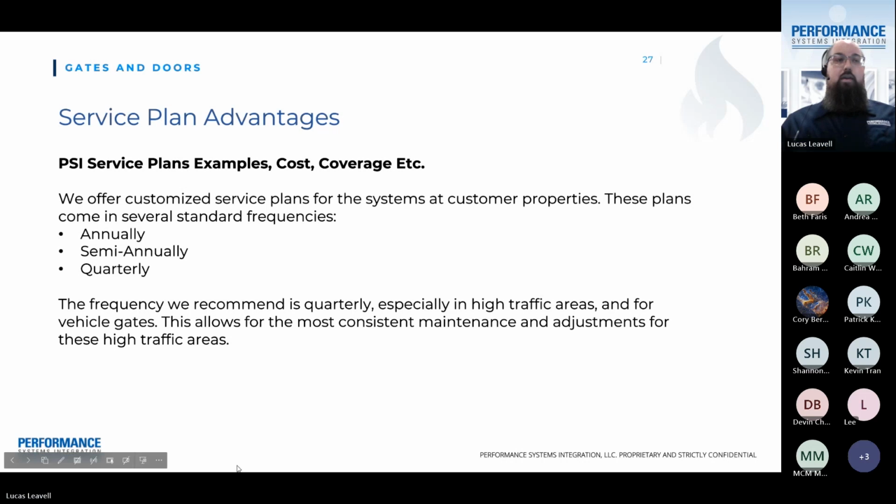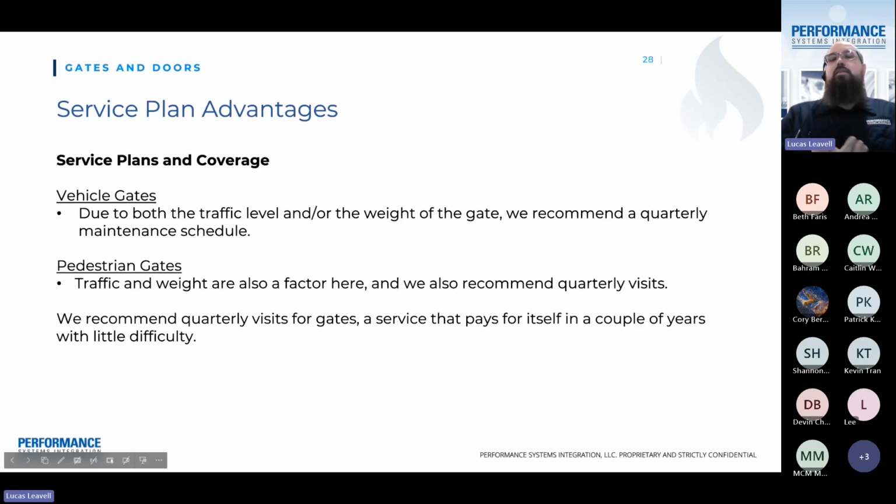So for vehicle gates, it's dependent on the traffic that it gets through. If your gate opens maybe once an hour, you probably don't need to have us go out there every quarter. But if you have the gate open, say, 100 times a day, quarterly inspections are strongly recommended. That's a lot of mechanical motion on the hinges. That's a lot of cycles on the motor of the gate operator. This will eventually, over time, wear down those systems, and they need to be properly maintained.